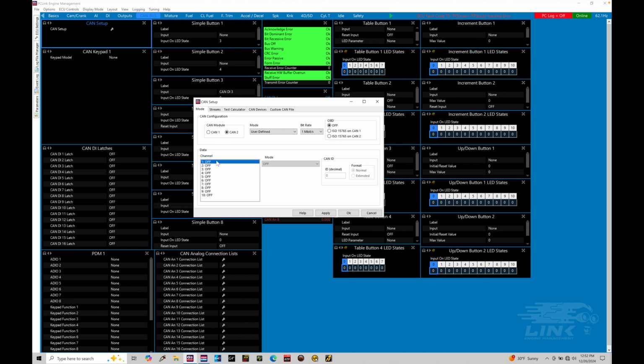We're gonna grab our first channel available. Under the mode, we're gonna set what we're working with here. So we're gonna scroll down our list and we're gonna find Link Razor PDM. So let's go ahead and select that. Now the transmission rate we can keep here at 10 Hertz, it's fine. The CAN ID, this is important. This is what we've set on the PDM Link software side of things, which was a value of 500. So again, that's traditionally what you always program for the first PDM module in your system.